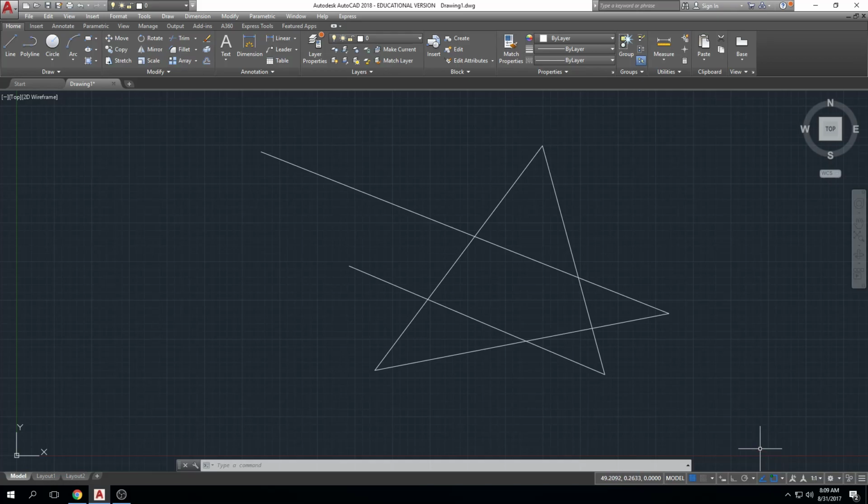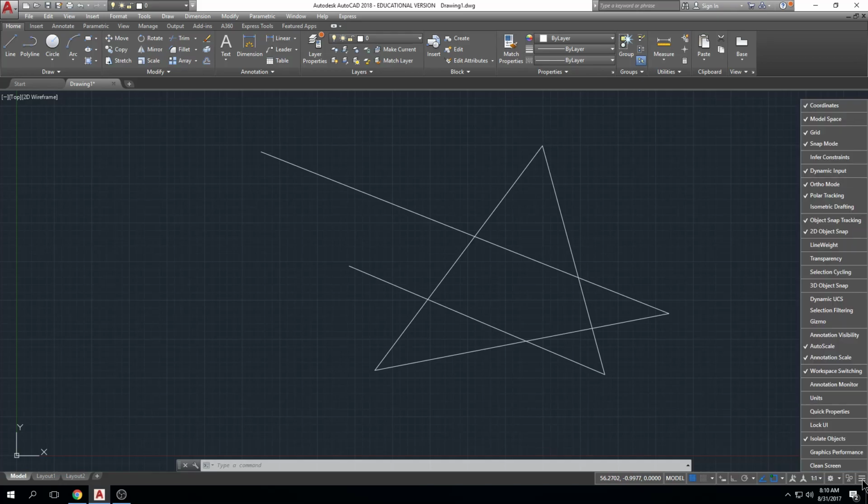Maybe to make your life a tiny bit easier, why don't you all right now open up AutoCAD, and if you click on these 3 little lines right here, we get this dialog box that pops up. And this will allow us to customize the object snaps that are down here, okay? So just make sure yours essentially looks like mine.